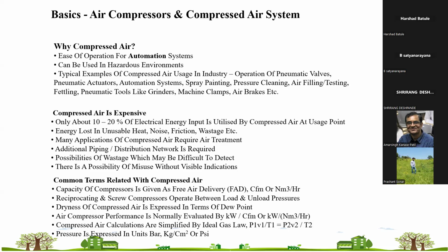One more thing: whenever we are generating compressed air, if we apply 100% of electrical energy, the output in the form of compressed air will be just 10 to 20%. The balance 70 to 90% is converted into heat, friction, noise, and distribution losses. So the user gets only 10 to 20% useful energy.